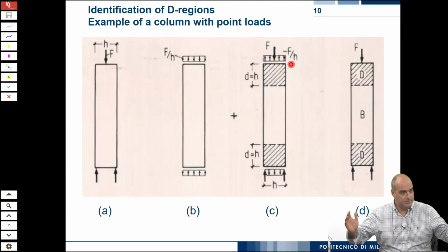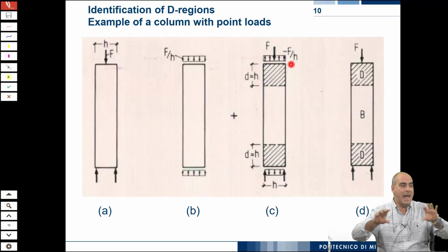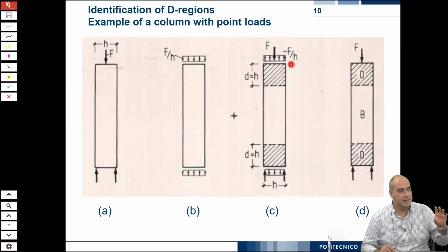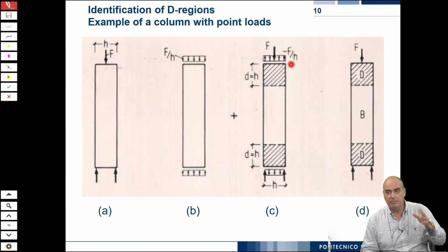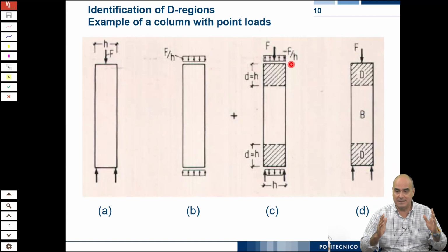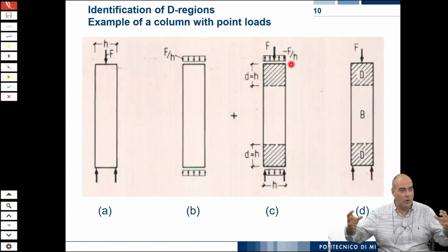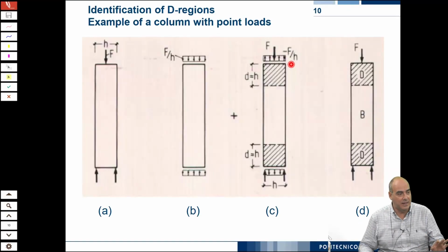You have a solid body with its length, like a cylinder specimen or a prism or whatever. Its length is sufficiently longer than the dimension of its cross section. At a certain distance from the cross section, whatever way your loads and stresses are applied on the edges, you do not feel the effects of local distribution.